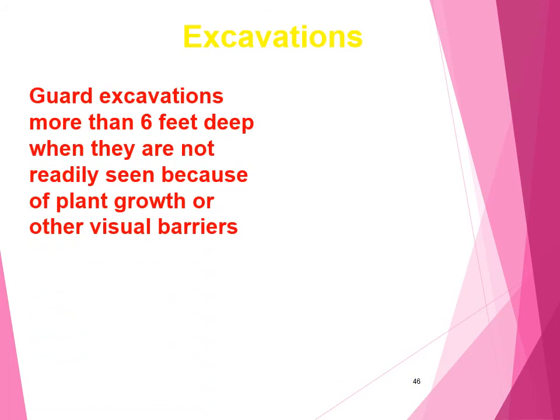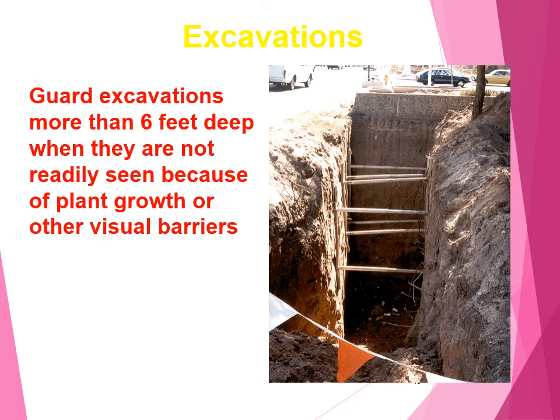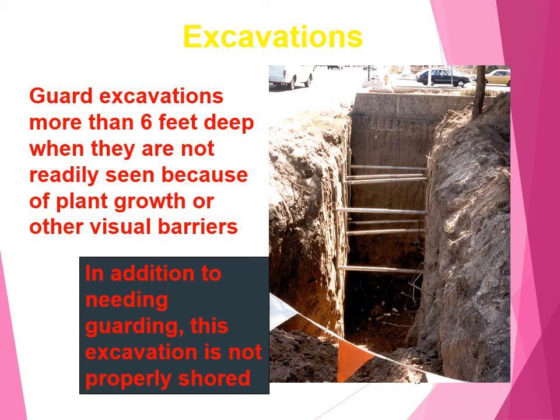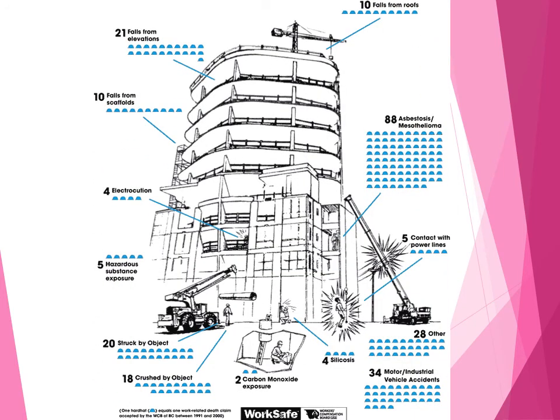Excavations. Guard excavations more than 6 feet deep when they are not readily seen because of plant growth or other visual barriers. This is the way it should be. In addition to needing guarding, this excavation is not properly shown. So be aware of coming close to such a type of excavation. These images will show you all the dangers involved in working at height.